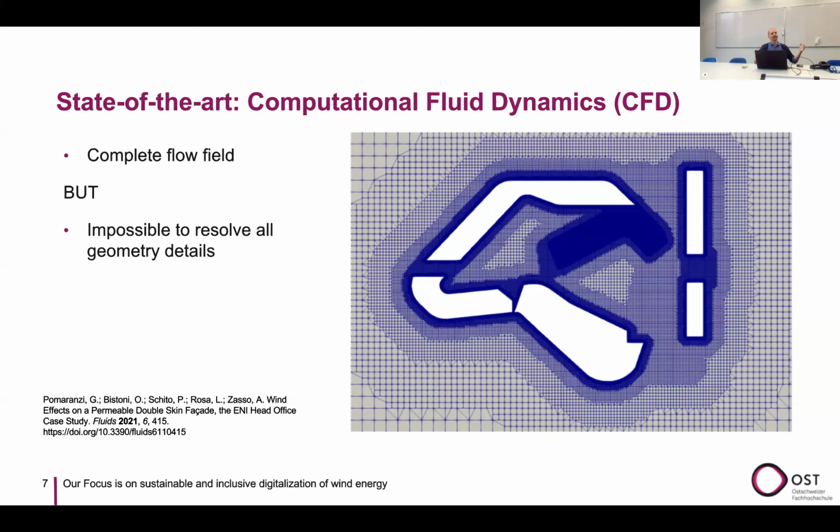So what it means is that the changes occur in time scales where there is a scale separation between what happens in small scale turbulence and big scale turbulence, so we can think of this one steady state simulation as a series of steady state simulations.